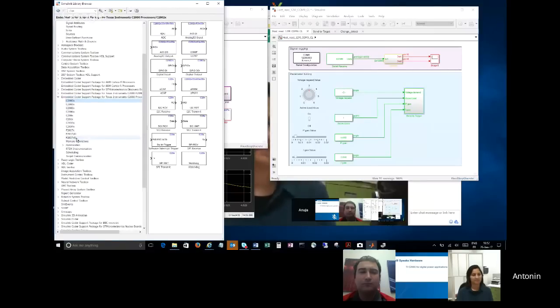And yeah, I showed only 2 blocks, but obviously, here is the Simulink library browser, and as part of this, we have support for all the C2000 variants. Today I showed the F28069M. We have support for ADC, DAC, CAN, SPI, SCI, software interrupts, CLA. You can also offload some of the code of your main CPU onto the control law accelerator. We try to be as complete as possible. This target is designed for industrial customers. We offer a lot of parameters on these blocks, and the goal is to go as deep as possible and give as much flexibility as possible to the target.